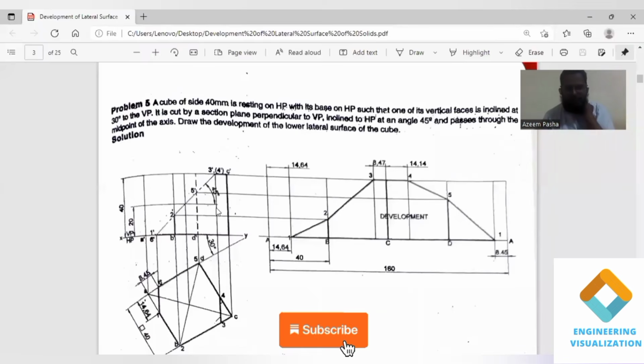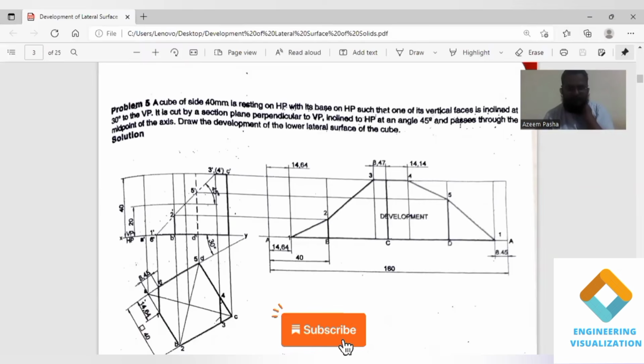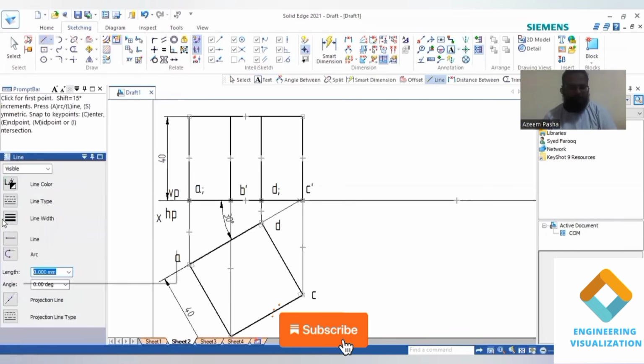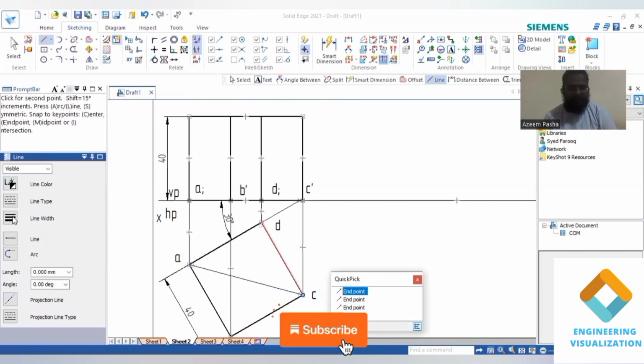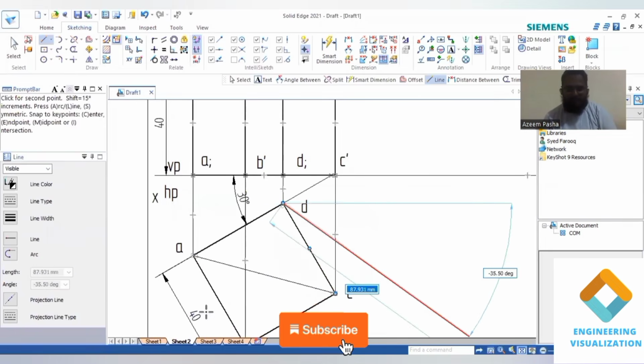Now you can see here we have to draw an axis. For that I'll be drawing thin lines here, that is diagonal lines, to find the center. And then I will draw an axis in the front view also. I will draw a thin line here because it is a prism. So cube is one of the prisms. Remember, the inside lines we are drawing should be thin lines.